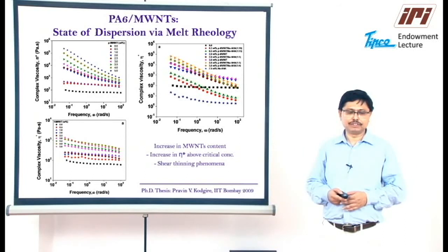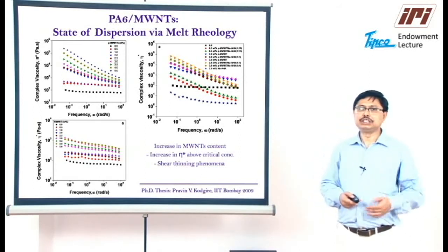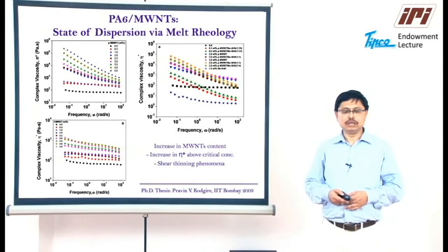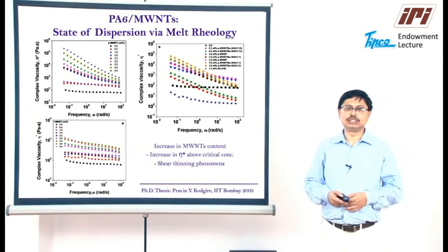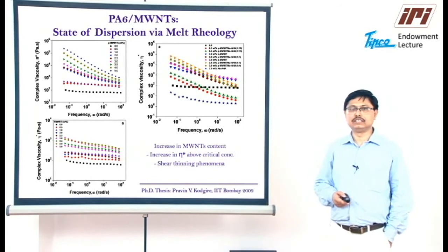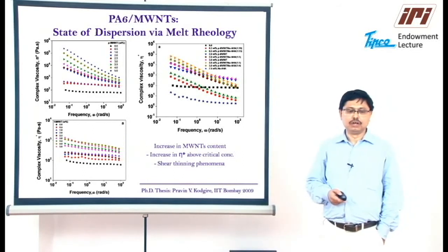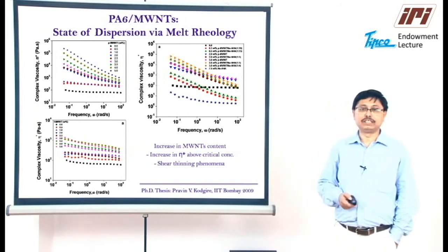In the complex viscosity versus frequency plot, there is always an increase at low frequency at a concentration between 2 to 3%, whereas in the case of NaHA modified multi-wall carbon nanotube material, we observe that even with 0.5% multi-wall carbon nanotubes, with various mixtures, the slope of the complex viscosity versus frequency curve increases as compared to the 0.5% based composites of either purified or functionalized materials.